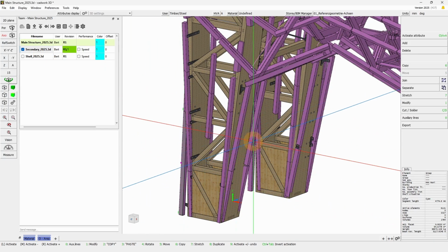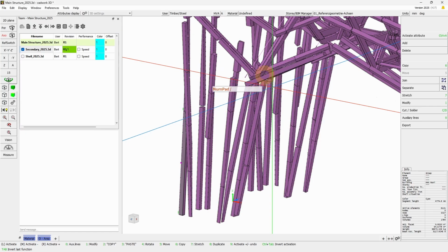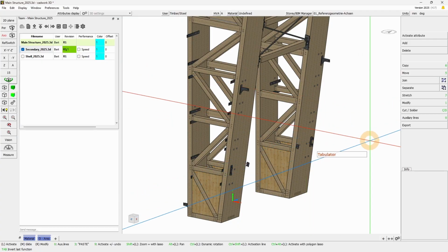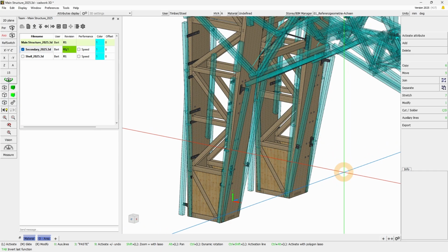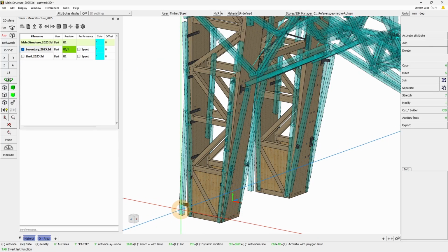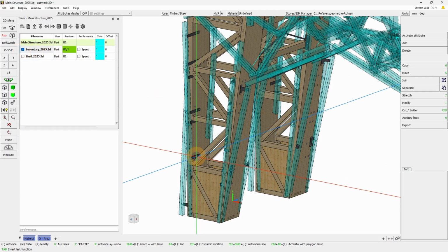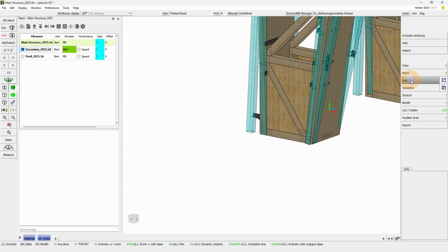By default, you see here that everything is joined together, so if I select one element, everything is activated. This allows you to quickly hide and focus only on this, or even to hide it to focus on your main project. And then you can bring everything back with J as you would normally do on an element from your file. Hiding the element will be a better and faster solution than unloading the file, because this will, of course, add additional loading time.